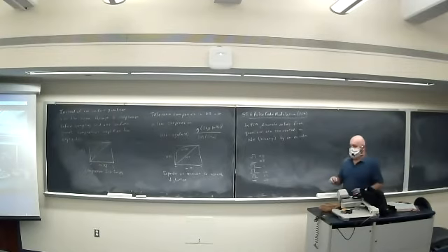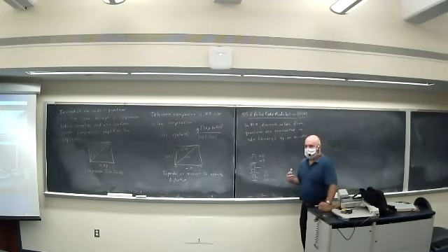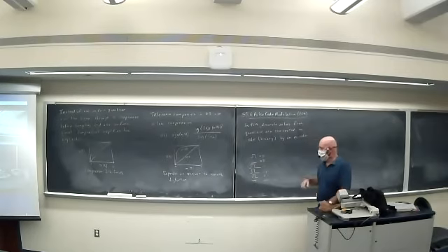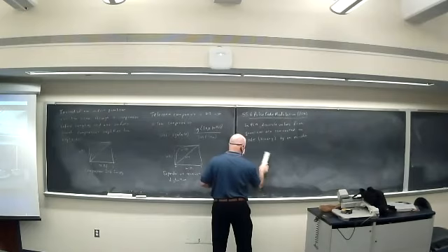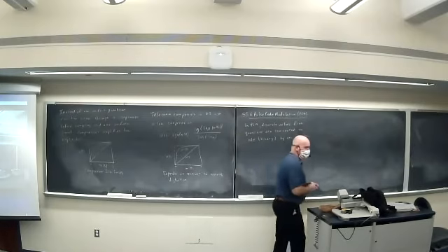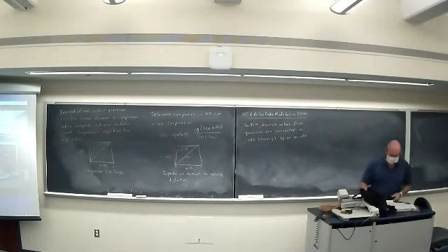So again, that's called M-level communication, capital M. So binary, or 4-ary for 4 levels, or 8-ary are the terms that are used, but I can get much greater binary throughput by using M-ary communication. But we'll come back to that later. Right now, we're going to concentrate on just this binary encoding.